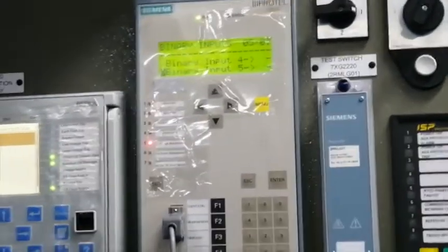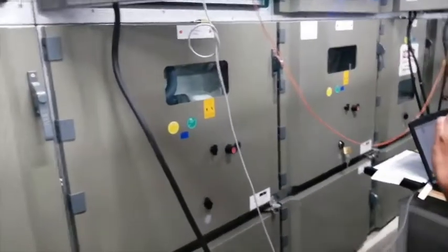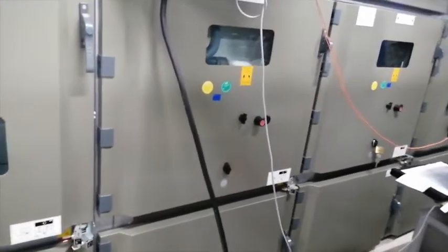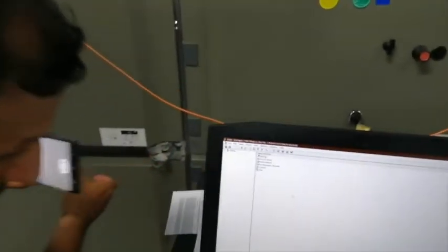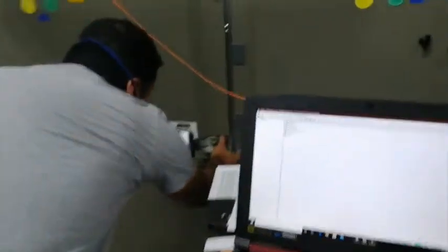But there is another interlock from HP that I need to have the earth switch close permission from HP side. That we already checked. So we will just simulate that so that we have the permission to close that. Okay, so I have to remove this line voltage. So I will remove this. Let's see. I don't now have the permission.